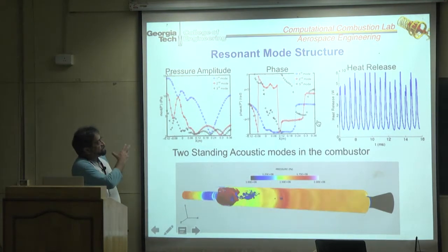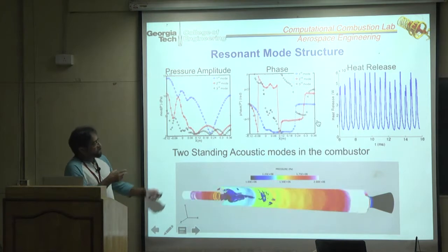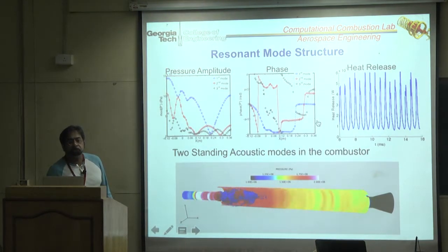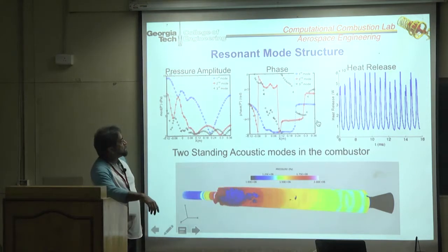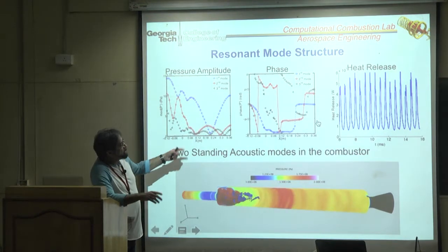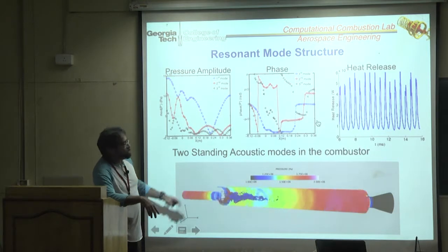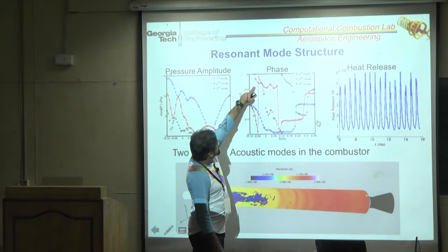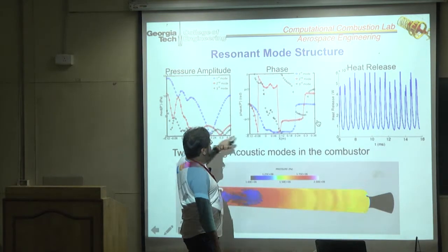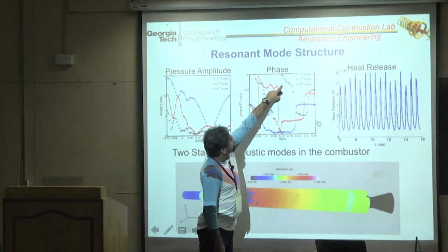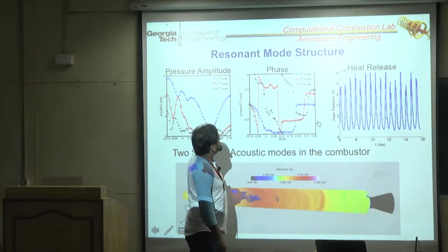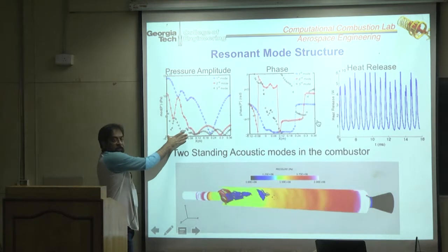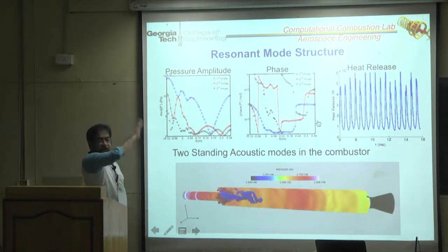So the point was that you can see a limit cycle heat release. The third one is very questionable. The third one shows 3 nodes, and the phase kind of lines up, you see some phase shift here, there's another phase shift here, but from 0 onwards is the inlet. There is no mode shape, it's just a traveling wave.